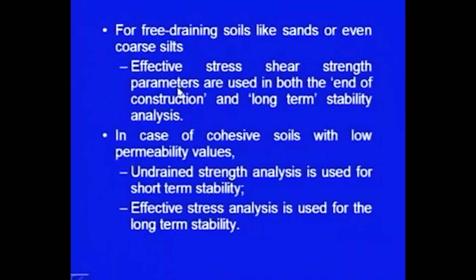So, this is what I was telling you. If it is a geological material like sand, gravel, or even coarse silt, within a very short time the excess pore water pressure which developed in the soil mass is going to dissipate, or you can say there is no development of pore water pressure.